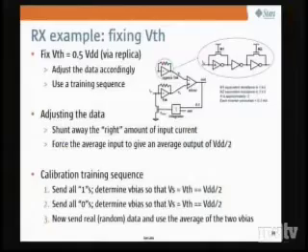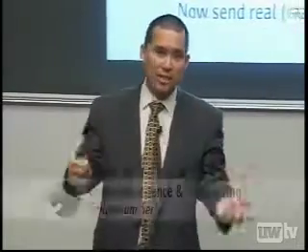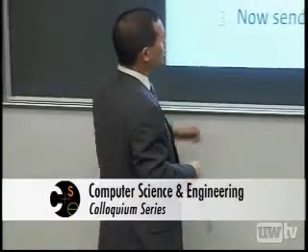So I better make sure that my input swing is perfectly centered around half VDD. And I can do that by having this device right here steal away exactly the right amount of current to force the input to be centered around half VDD. And I can periodically recalibrate the system to make that true. Okay, now how do I do that? Well, one thing I can do is an analog feedback loop, and burn a lot of power and have a lot of complexity, or I could do a digital circuit, which is what we actually did.